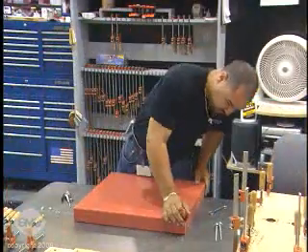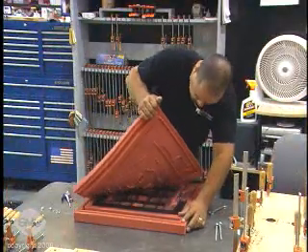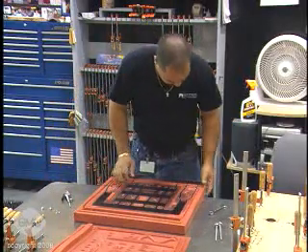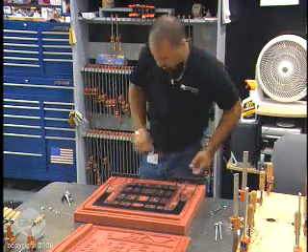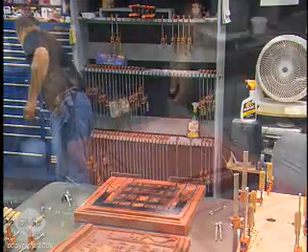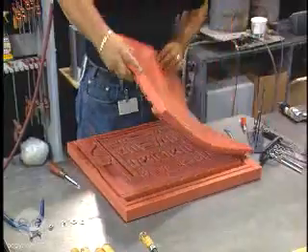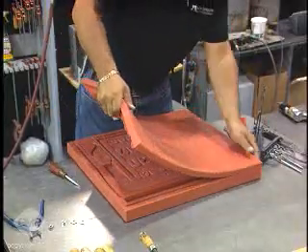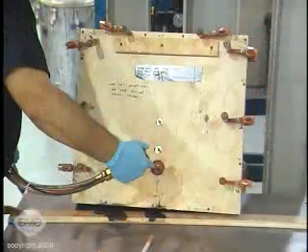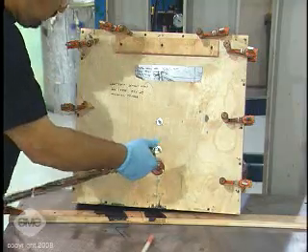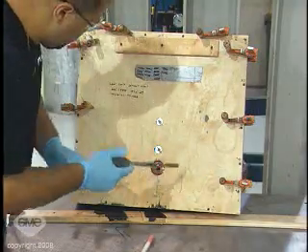RTV tooling can be used to mold small to medium quantities of parts out of a large variety of urethane, epoxy, or other polymer materials. RTV tooling can typically be used to mold several parts before replacement becomes necessary. The number of parts produced depends on accuracy and finish requirements and the complexity of the part geometry.